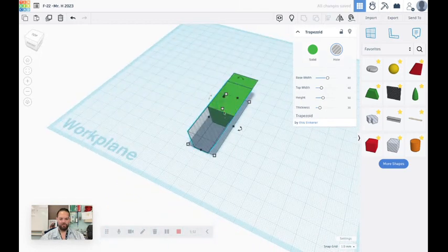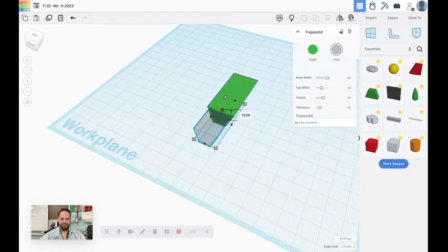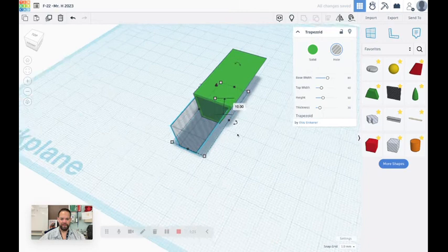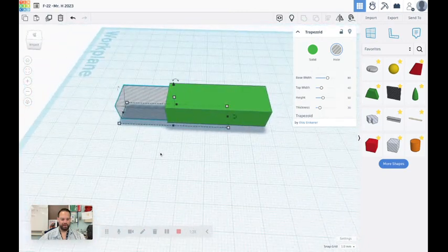And then we're going to use the Alt and the Shift key, okay? And we're going to just drag this inward and make this about 10 millimeters, okay? So now when we look at it from the side view again, and now use the